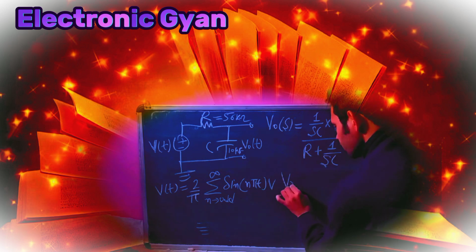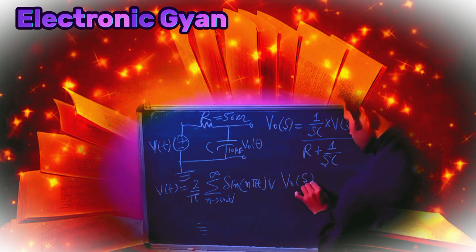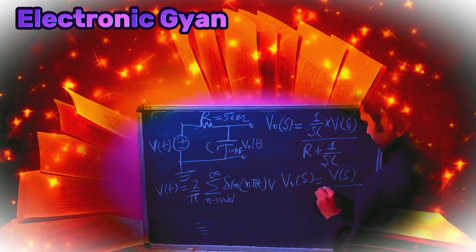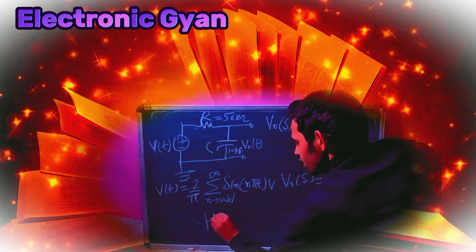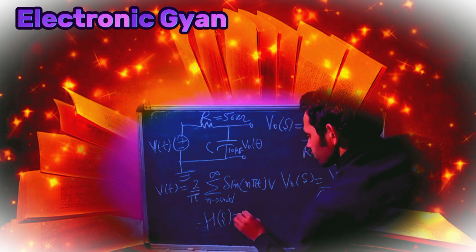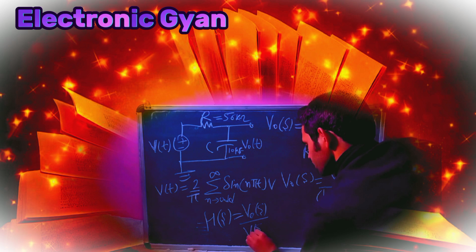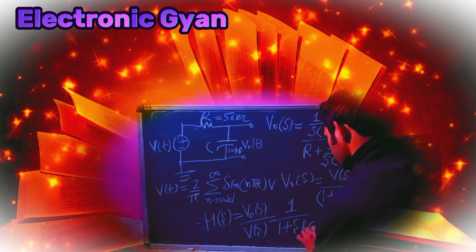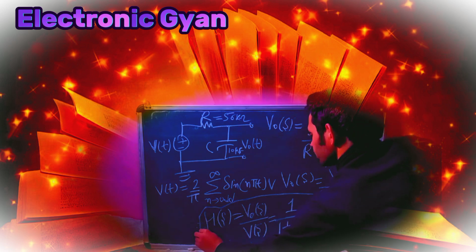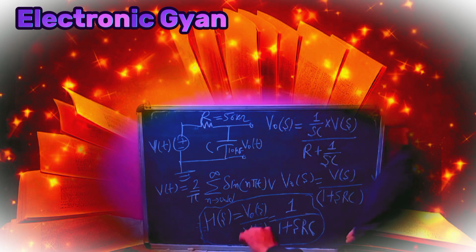From there we get V0(s) equal to V(s) divided by 1 plus sRC. So the transfer function is H(s) equals V0(s) divided by V(s), equal to 1 by 1 plus sRC. This is the transfer function we have obtained for this system.